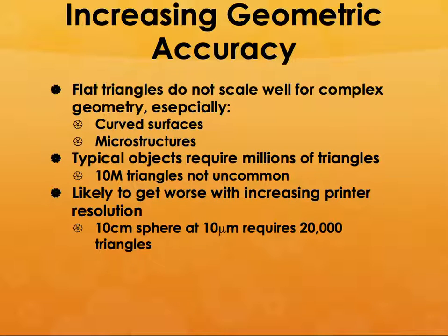So the more triangles you have, the larger the size of the file. And if you have a flat triangle, and a very complex geometry shape, especially curved surfaces and microstructures and things like that, it really cannot exactly convey that information to the machine actually building this part. And even with higher and higher printer resolution, it's not going to be very accurate.